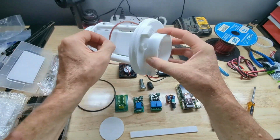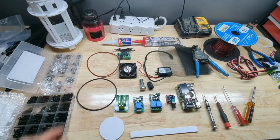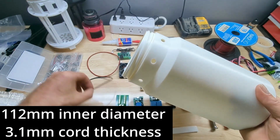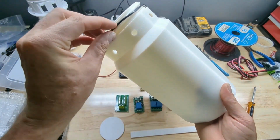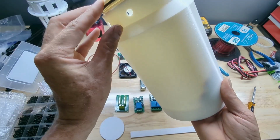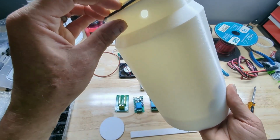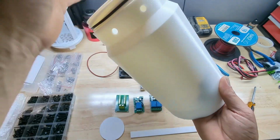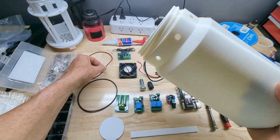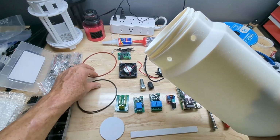Now, this top one, this black one that we have here, actually goes on the top of this enclosure. So when you put your dome on, you screw it down, it'll seat tightly to that. Now both these rings, the top O-ring, the cap seal that we'll call it, is a 112 millimeter inner diameter. So it just sits on this ridge, and when you put the cap down, it seals tightly on that. The thickness of this cord is 3.1 millimeters, but I will have parts linked to these that you can buy directly on Amazon.